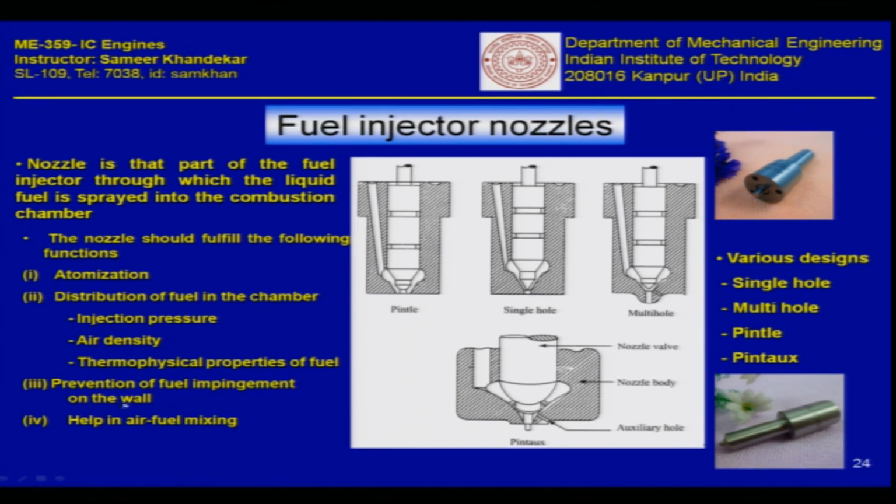It should prevent the fuel impingement of the wall, because if the spray length is so much that it actually impinges the wall of the cylinder, the wall is cold, mind you, because there is some cooling water also going around. So, you will have liquid which is sprayed on the walls, which is detrimental to not only the tribological health of the cylinder, but also the combustion efficiency, because you are spraying actually diesel on the combustion walls, which are much colder than the inside of the cylinder, and therefore you may have chances of incomplete combustion or carbon being deposited on the walls, which will also affect the overall efficiency of the engine.